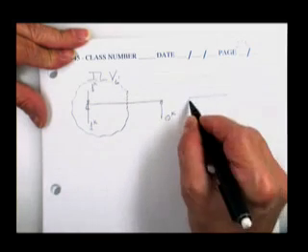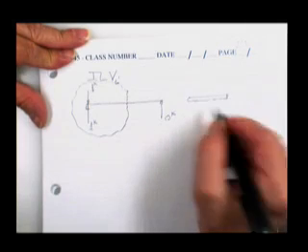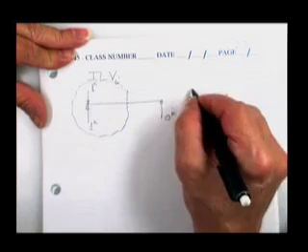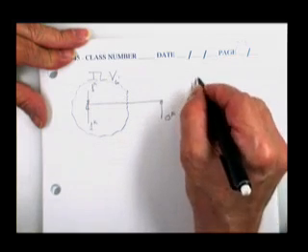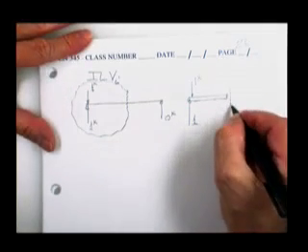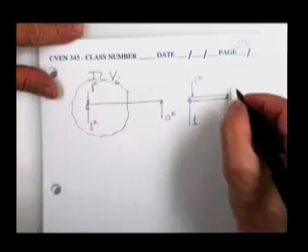Here is your free body. Interesting. How much shear is caused at the 6-foot mark when the beam is loaded with the 1 kip load just barely on the span? 0 is correct.